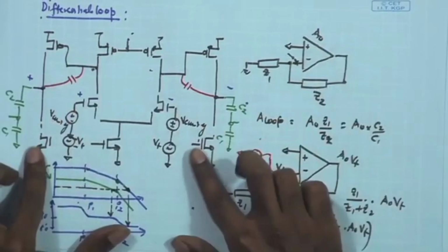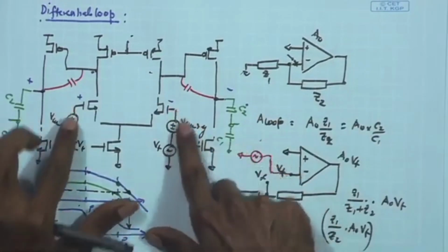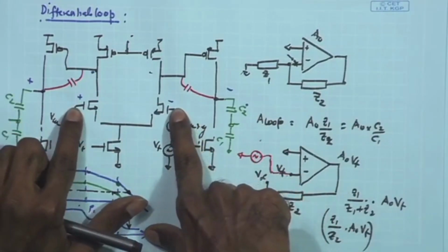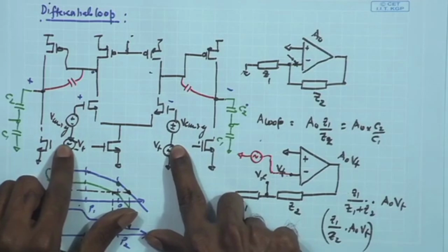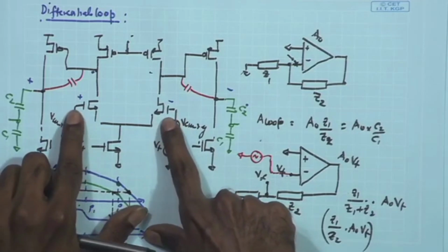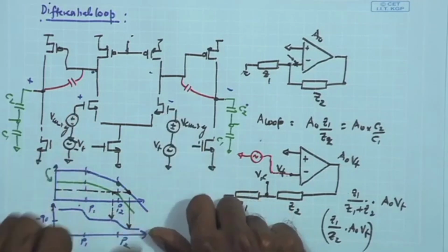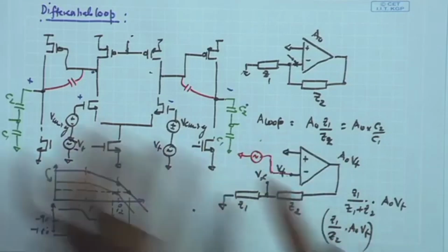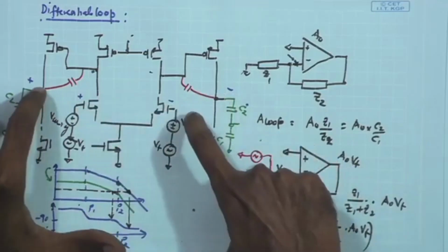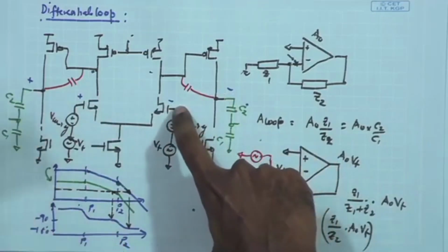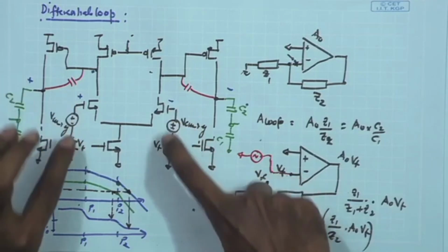Now, if I connect that RF and then assume that this DC potential will be determined by that RF, what will be the problem? If you apply an AC signal with 0 DC, the DC potential at the gate will be 0, right. So, if you assume that you have put the RF, the feedback resistor between the output and the input and the positive output and the negative input, like we did for biasing, and then you apply a test signal,